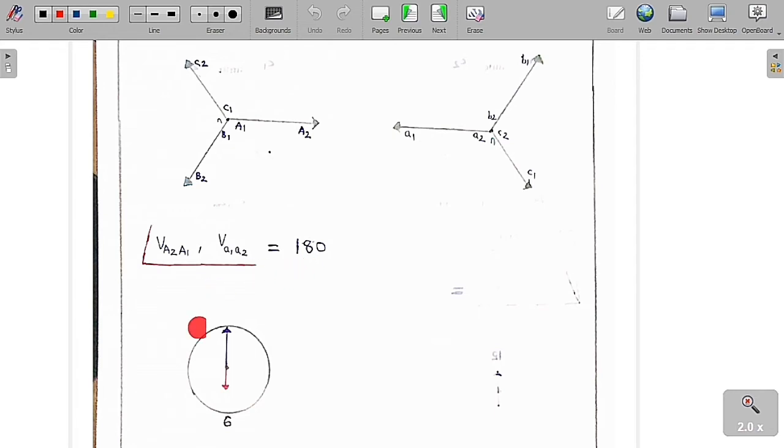So therefore, as I have already told you, the HV phasor is fixed at 12 o'clock. The LV phasor is the hour hand and the HV phasor is the minute hand. So this is our HV phasor, and we are going to fix it at 12 o'clock. And here there is a 180-degree phase shift. 180 degrees means for the LV winding we have to give a phase shift of 180 degrees, so we are going to get 6 o'clock. So this is a 6 o'clock representation.